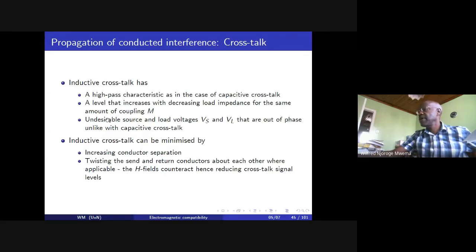That is phase A, the yellow phase, the red phase, and the blue phase will not be connected on the same spot or on the same position at two different pylons, so to speak. This is usually done to reduce the inductance of the transmission line.